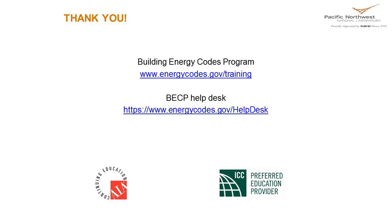There are limits in the code, and it depends on your climate zone. So you might not meet code with a non-labeled tested NFRC product. It all depends, and it depends on what else you're doing with that building. So that's why I go on the side of find an NFRC rated product right off the bat. So you're not in a situation that you are deferred to have to use those energy code defaults and you're not in compliance, because you're going to have to go back and redo it and find some products that do.